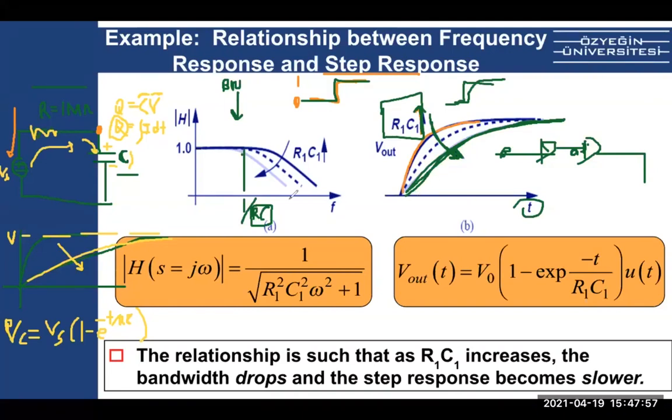Well, in the frequency domain, that corresponds to bandwidth, as I mentioned. Now, small RC means the bandwidth is big. That means your bandwidth is not here, but your bandwidth is here. Okay, that means all the signals. Remember the example I gave you, this impulse, you want to host that. All the frequencies you want to go through. So this time domain impulse can only go through if RC is small, so that the bandwidth 1 over RC is big.